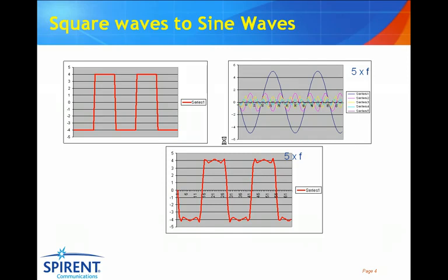What I want to show you here is that basically the human eye is more susceptible to the lower frequencies within the video spectrum. If you look at a TV picture and notice that it's a little bit softer, it's softer because most probably too many of the high frequency components within the picture have been taken out. The more high frequencies within the picture, typically the sharper the picture is going to look. Within MPEG, one of the tricks that's applied to reduce the amount of information is to strip out some of these high frequency components. Now, let's take a look at the square wave if we reduce the amount of information.